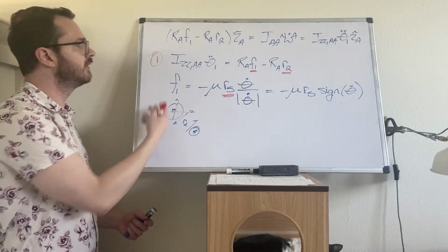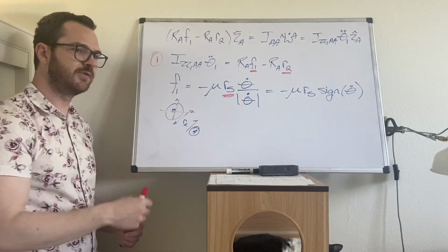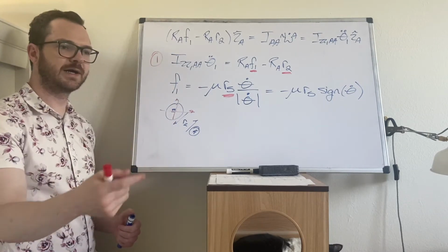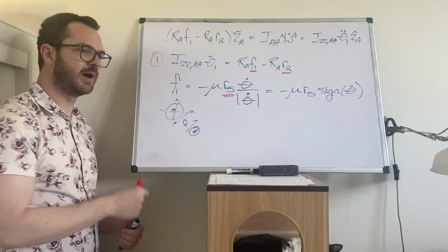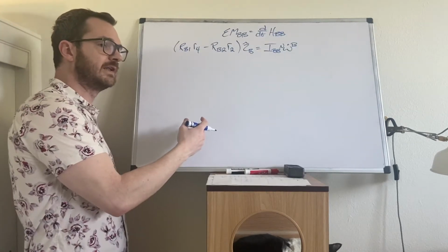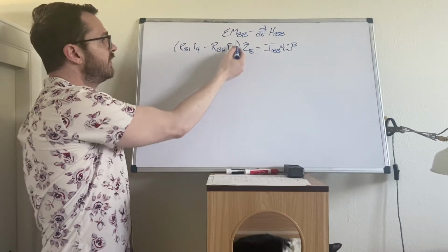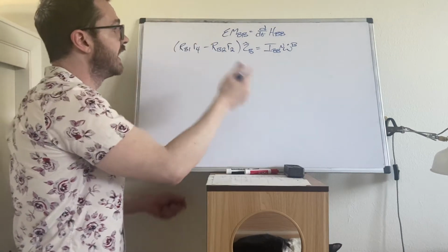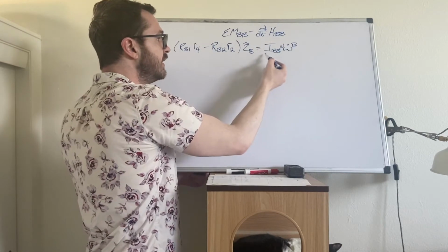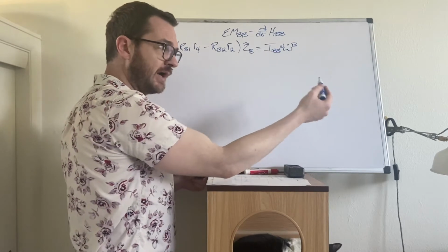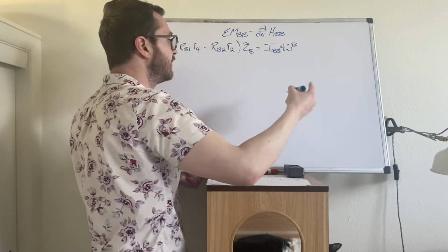What we're going to do, let me clean this up, is Euler's second law for body B. Here's Euler's second law for body B. You should have this in your notes already, the sum of moments on B about B, and of course, d/dt of H_B about B. Symmetric body, we're going to say the cross product term is 0.